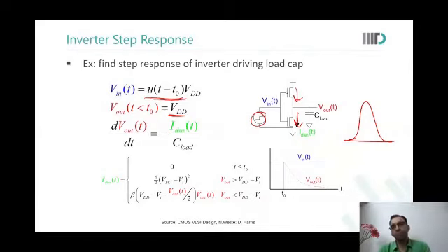Okay. So what is being said is that because there is a load over here, this would prevent any change in output voltage. This will resist any change in output voltage. It will start to sink its own charge so that output doesn't change. And therefore, my delays would increase, and therefore, this curve would become wider. Is that what you want to say? Yes, sir. Okay. And anything else would happen?